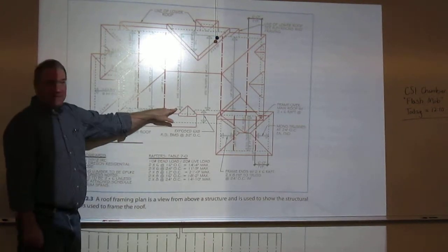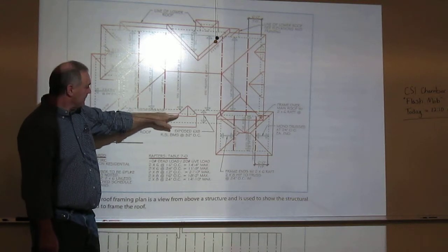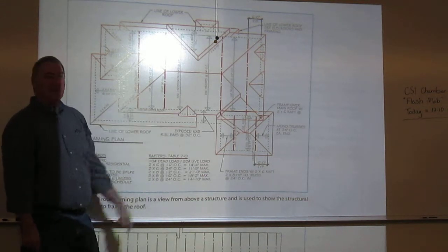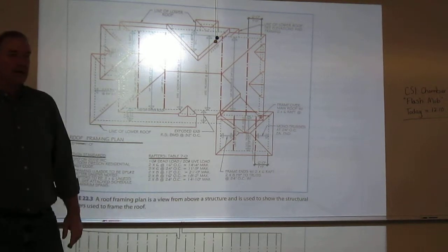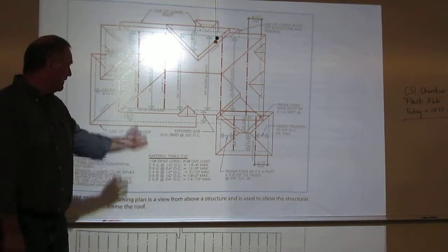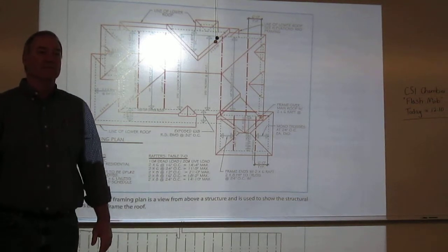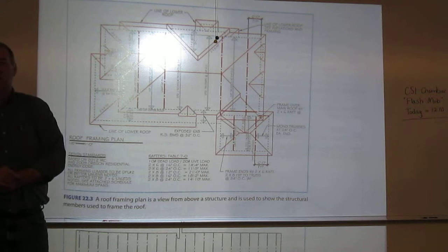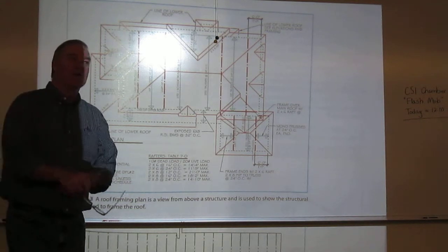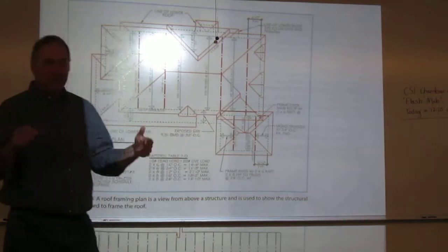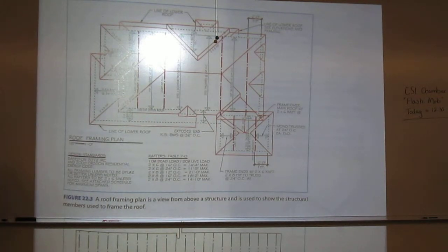First thing is we've got an open-faced arrow. If you use your polygon command, we want this to be a 1/4 inch. Why would I use the polygon command? Because in essence that arrow is an equilateral triangle. Or you could do a standard triangle if you wish, where you make it a 1/4 inch and then put your width at 1/3 of that if you wish. Now, if I need to print a 1/4 inch, what size do I need to make this arrow? Times my DSF. What are we printing this at? Oh, doing a 1/4. Okay.